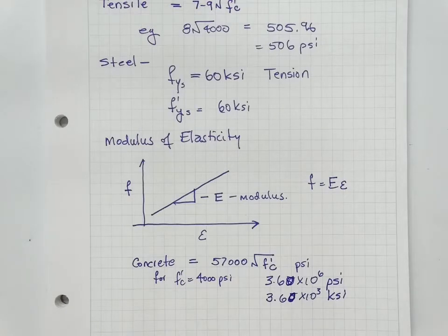When we talk about compressive strength, we said 4,000 psi. It's also 4 ksi. And you need to watch the units, because it's very easy to fall into that trap and be off by 3 orders of magnitude, because you had something in kips and something in pounds. Similarly, some dimensions, the span of a beam in feet, some dimensions, the width of the beam in inches. So you need to make sure there's a conversion in there.